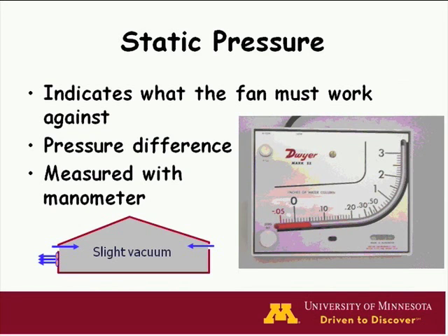Now, there are other factors that will impact the pressure difference that the fan must work against. Wind blowing against the outside will reduce the airflow rate. And if we've got a building that has inlets that are too small, that will increase the static pressure and reduce the airflow rate. But the static pressure can be measured with a manometer, as shown here, and used to keep track of how the system is performing in the field.